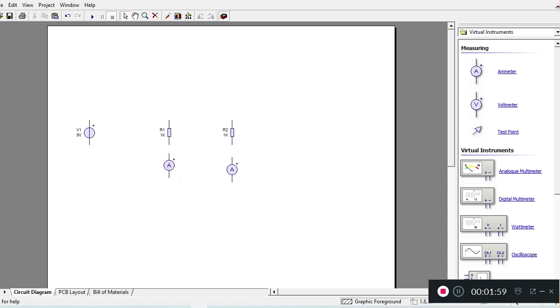Okay, and then the next one is going to be here. If you don't like the position, you can just rotate it using the key that I just clicked on. Okay, so now from here, I can just connect my components to make my circuit. Any unwanted line, you can get rid of it by typing the escape key on your keyboard.